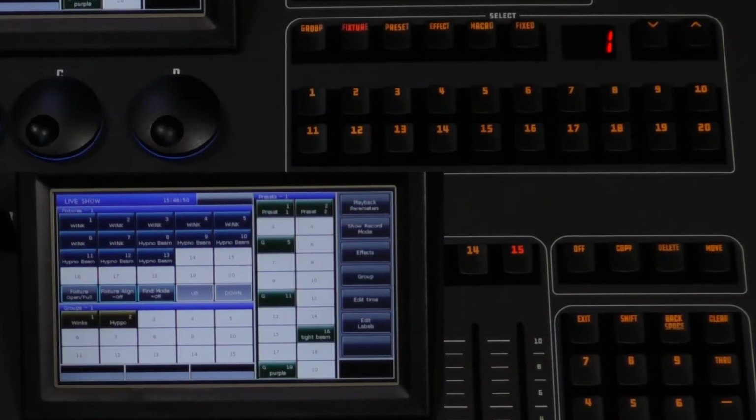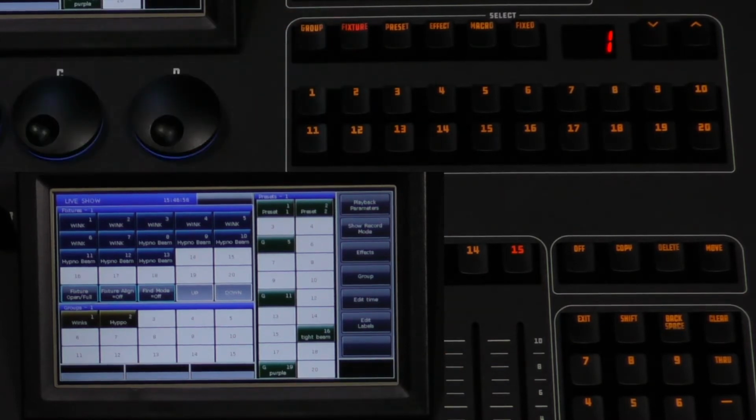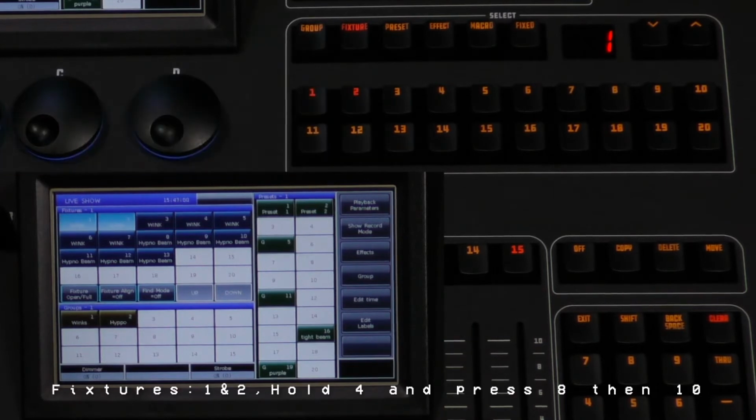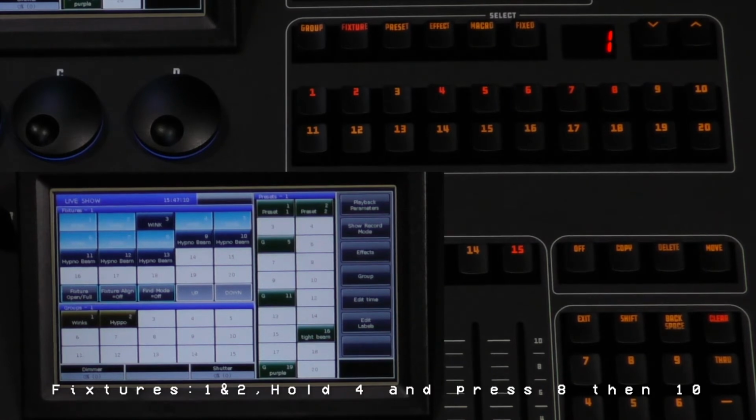When using the selection area, press the fixture button, and you will see that it is selected by the red LED indicator light. Then press 1 and 2, and then press 4, and while holding it down, press 8, which will select the range of 4 through 8. Then tap 10, and you're done making your selection.